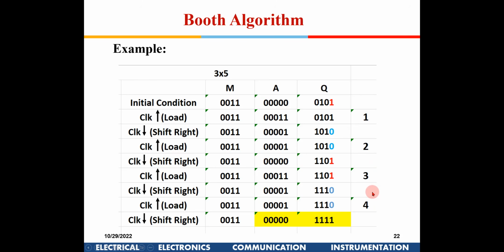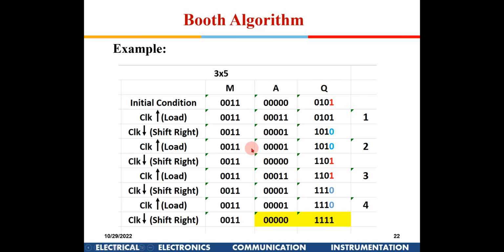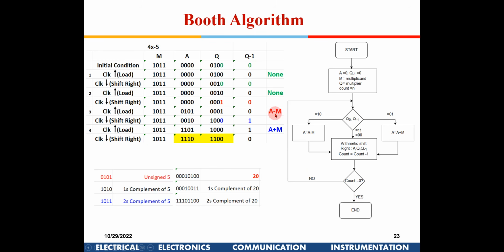So this is okay. Now this Booth algorithm that we talked about, and this diagram, is good enough only for unsigned multiplication. This algorithm gets a bit modified when we are talking about signed multiplication. When I say signed multiplication, then this 1 0 1 1 indicates -5 here, right?